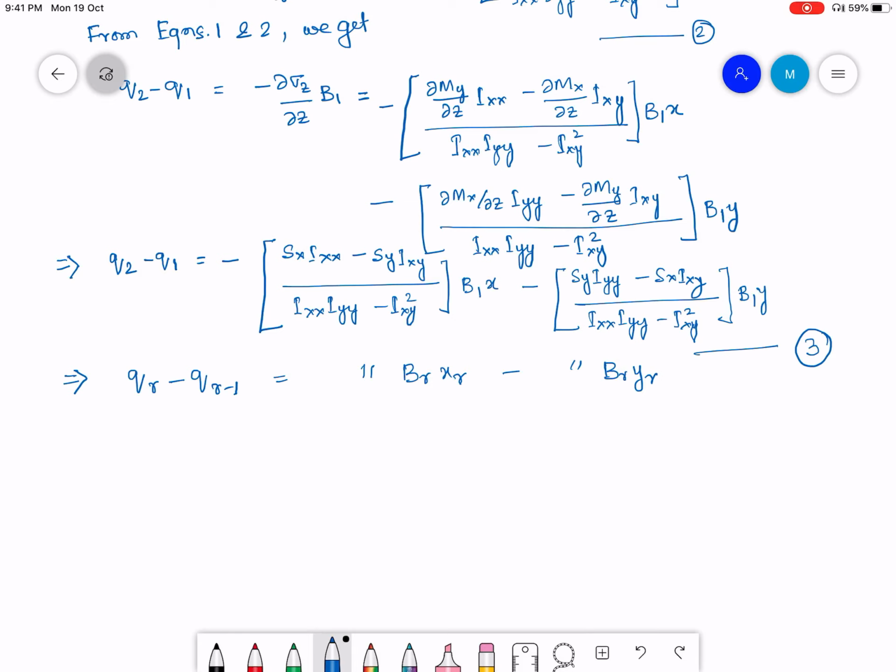If you remember, the shear flow in a non-idealized cross section, not simplified using skin stringer idealization, had terms that were actually integrals, x ds and y ds, and q was a function of s.